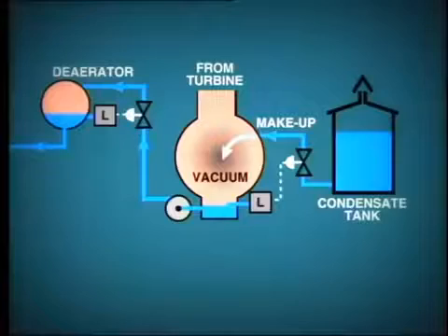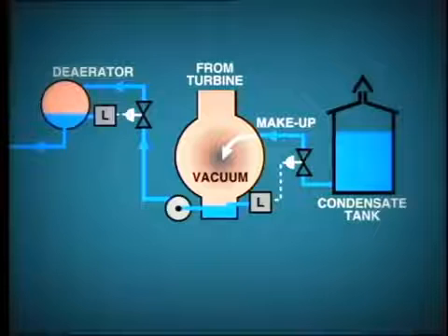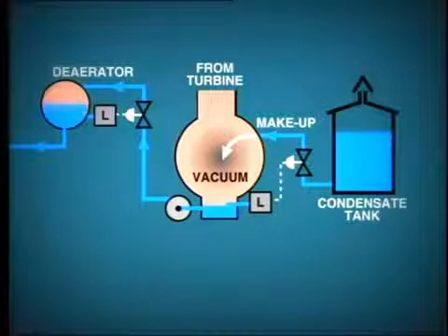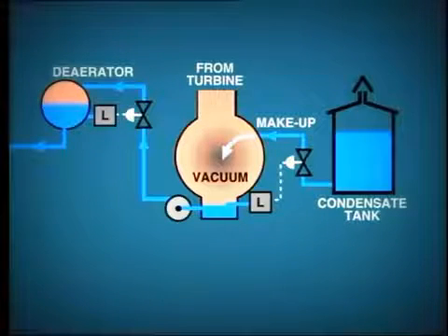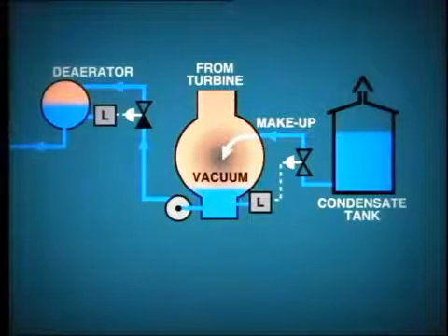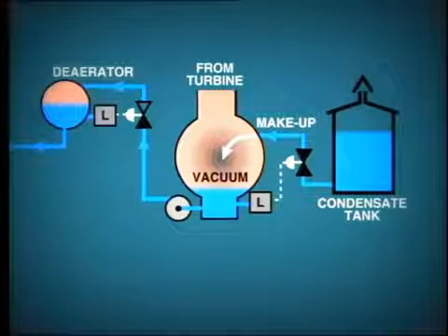When load is increased, the opposite situation takes place, as the boiler water level increases due to swell. In this case, the boiler feedwater control valve reduces flow, the de-aerator level tends to rise, so decreasing the de-aerator control valve opening. This causes the hot well level to rise, thus causing the makeup valve to close completely.